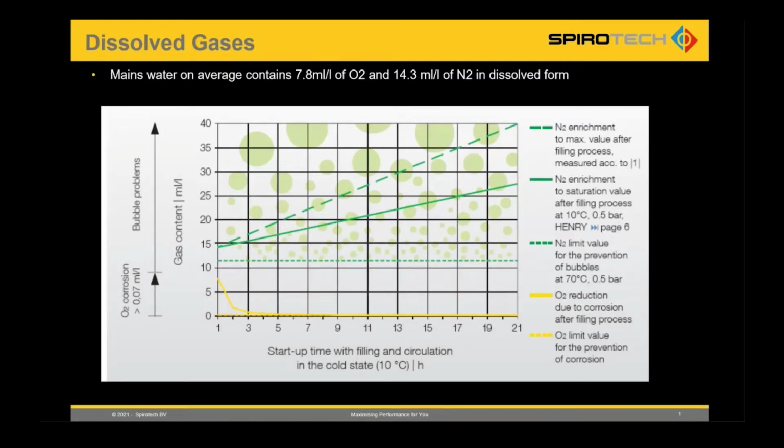And then once you've got that, you'll still have gas and air problems in the system because you've still got nitrogen and so forth. You need to get rid of those. Those are the green lines on the graph, if that's still up and if you're interested. That's what the deaerator or degassing solution will be looking at, the green, the nitrogen and so forth, not the oxygen specifically.